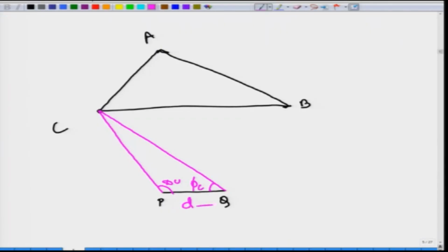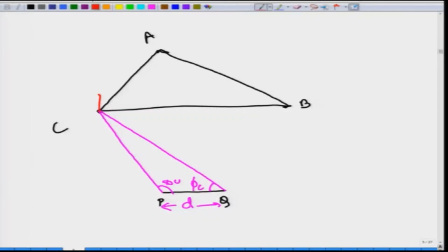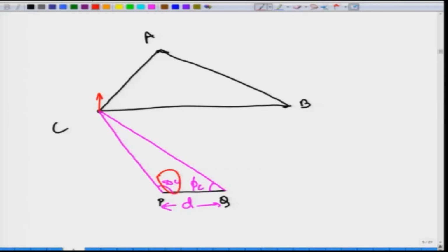You are taking the angles, and you do not need any linear measurements in this case, just one measurement, that is the distance PQ. So, these are 2 points that you have fixed. Now, you go to the first point, P, and you take the angle of one of your stakes. You had put a stake here, you went to this point P and took a reading to the stake and measured it as theta c.